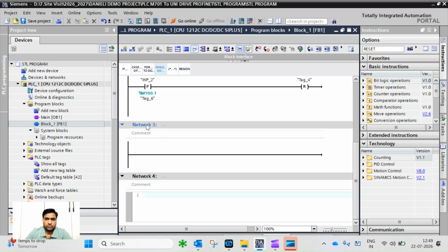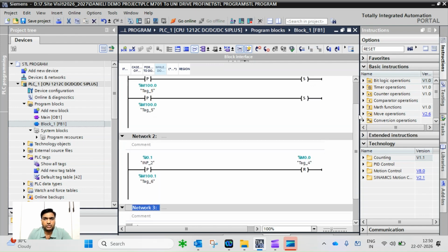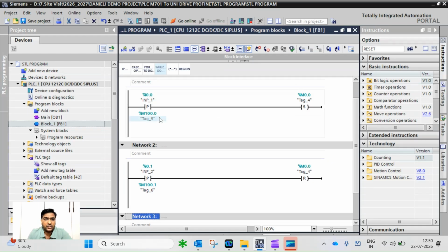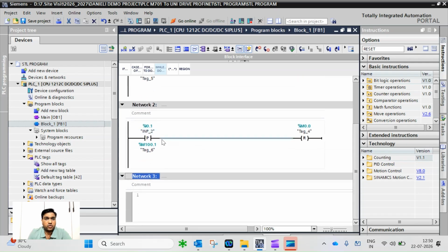We can use the if condition. How? When I0.0 turns on, what will happen? M0.0 will be set, meaning turn on. So if we get any output, that output will be on. Now in the second line, when I0.1 turns on, what will happen? M0.0 will reset. So I am writing the same thing in SCL.